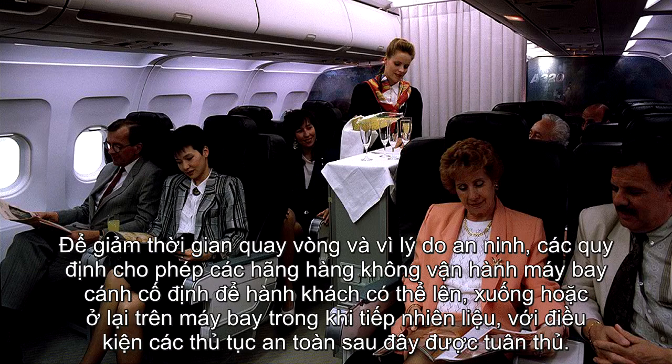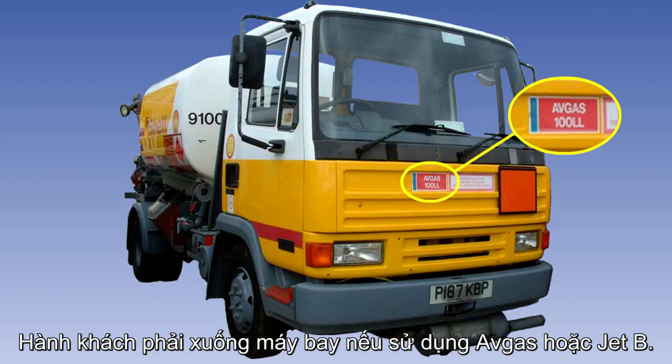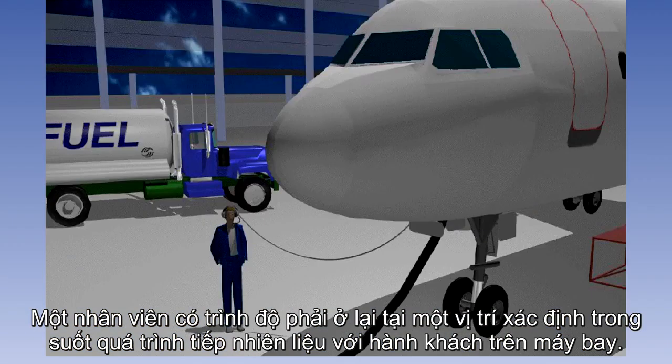To reduce turnaround time, and for security reasons, the regulations permit airline operators of fixed-wing aircraft to allow passengers to embark, disembark, or remain on board during fueling operations, provided the following safety procedures are followed. It is not permissible to refuel fixed-wing aircraft with less than 20 seats while passengers remain on board. Passengers must disembark if avgas or Jet B is being used. One qualified person must remain at a specified location during refueling operations with passengers on board.